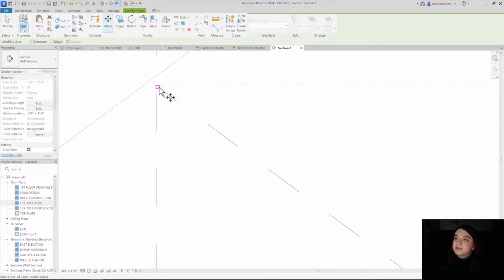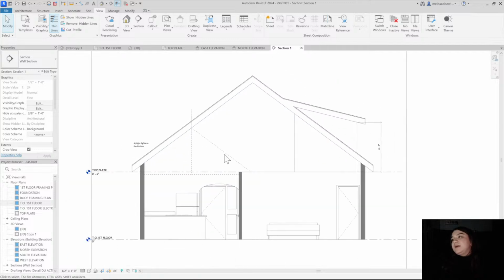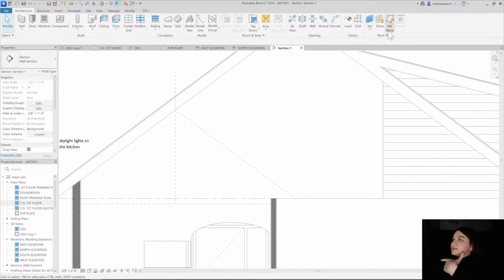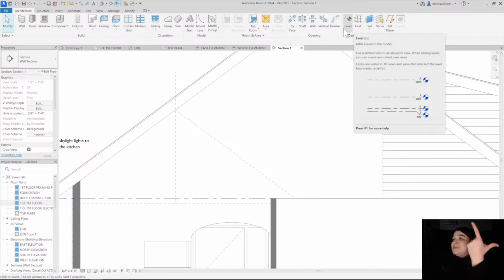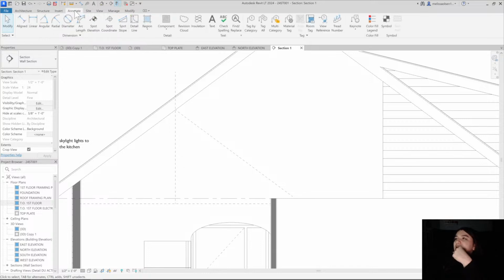And we're gonna want this to be like that. And of course, this is just reference lines. They're not reference lines in Revit. They're actually detail lines, which are 2D lines, and I use them to create reference lines for myself within a project. I think there is a way to actually create reference lines, but I don't utilize them. I think that's the reference plane, which we use.